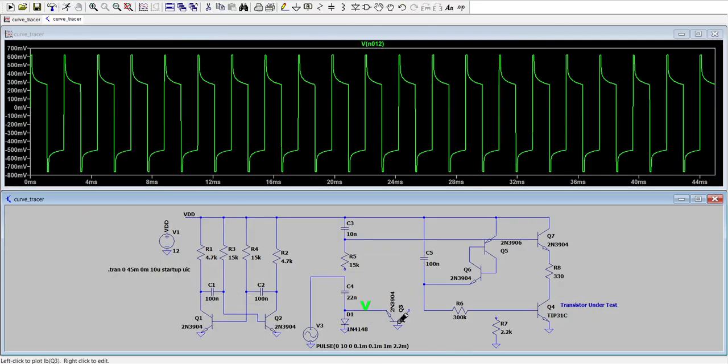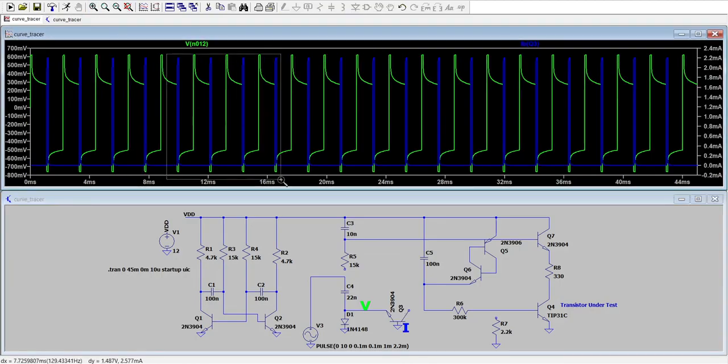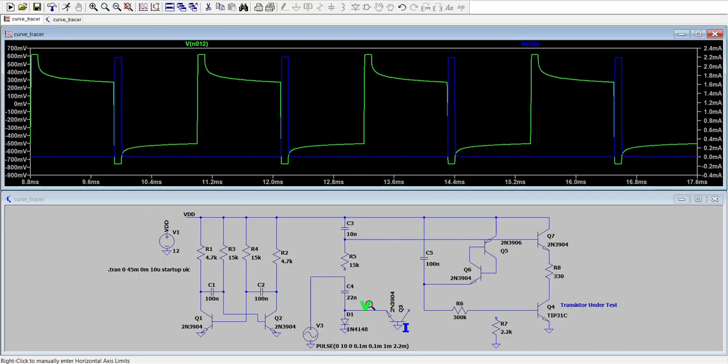Let's now look at the current of the base of Q3. You can see that there is a current flow. Indeed, when this node here reaches a sufficiently negative voltage equal to the PN junction drop, since the base is tied to ground, a positive potential is applied to the base emitter junction, and current will flow through it for a small time. This makes the transistor turn on.